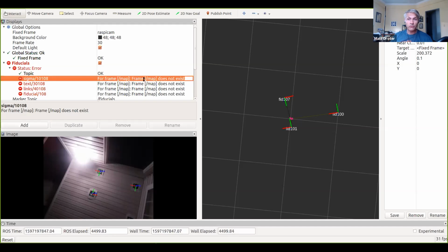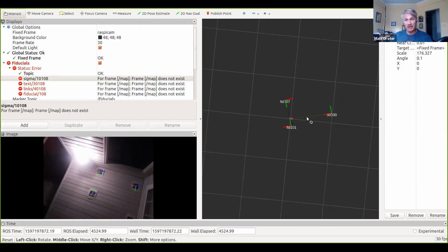And then you'll use the fiducial SLAM from Ubiquity Robotics, and that's kind of what you have running here, I think. And you need to calculate the distance from your map frame to your base link. But what we do is we go map, ODOM, and then base link.